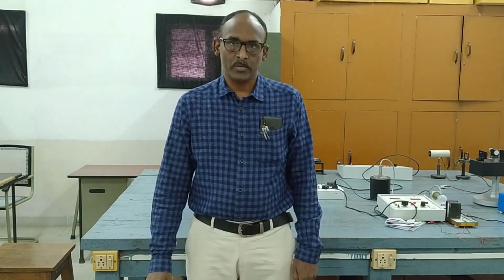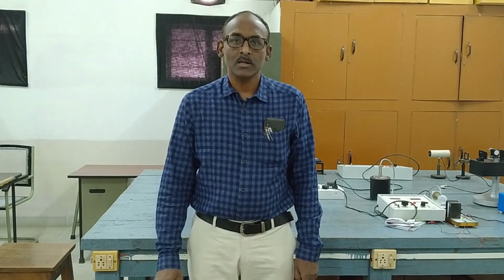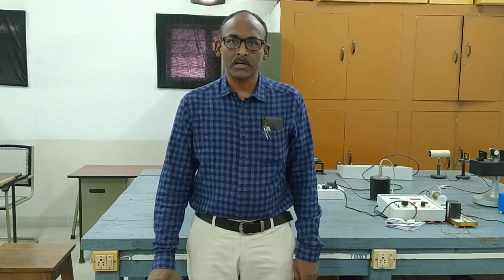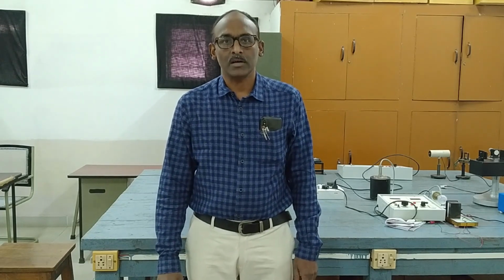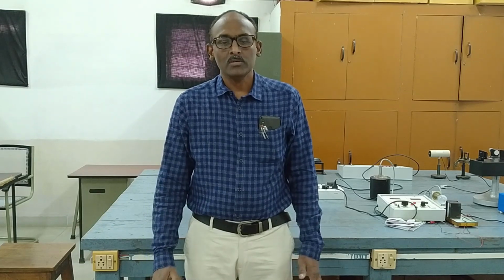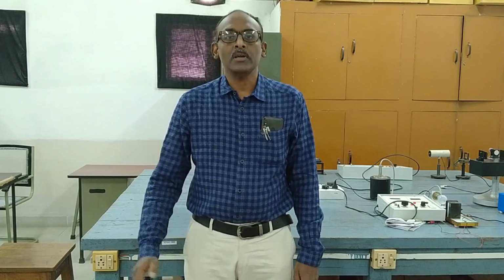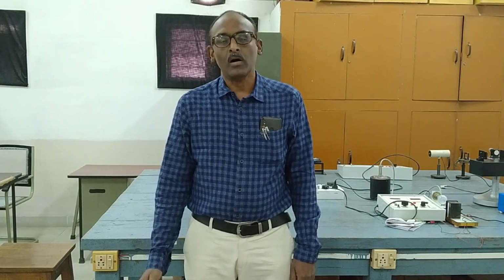And now we will see another diode called the photodiode. A photodiode is also a p-n junction diode made of semiconductors, but operated in reverse bias. A photodiode is also called a photodetector or photosensor, and these are used for sensing requirements. In optical fiber, we use an LED as a source and a photodetector, that is a photodiode, at the receiver end. So basically a photodiode converts incident light into electric current or voltage.